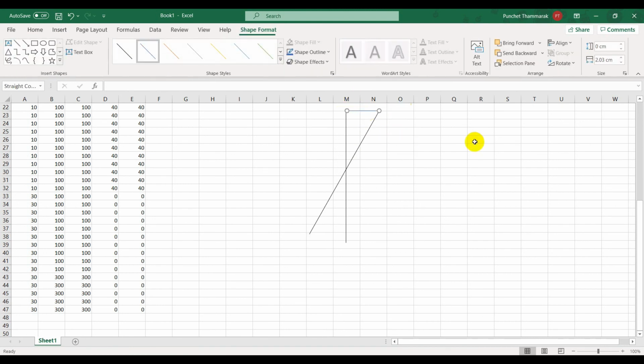I say that the strain at the top I can vary, and as I do that, I'll be able to adjust the neutral axis at the same time. You can either say that the location of the neutral axis is from here to here, or you can say that the strain at the top is this much or this much. It could be done either way.